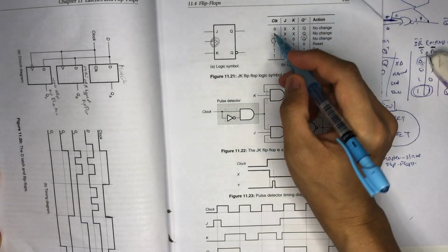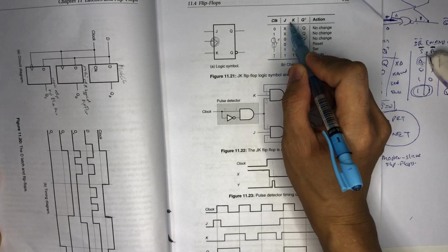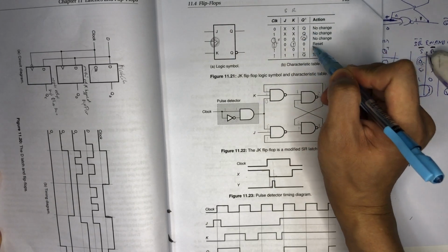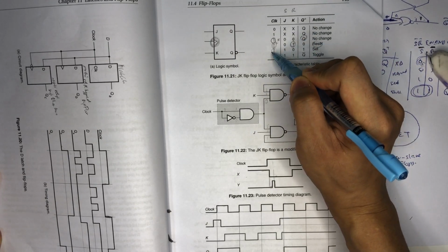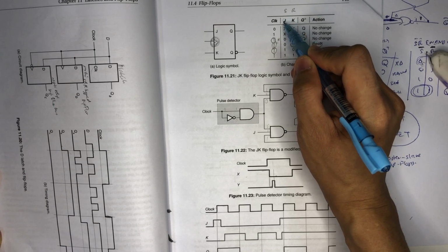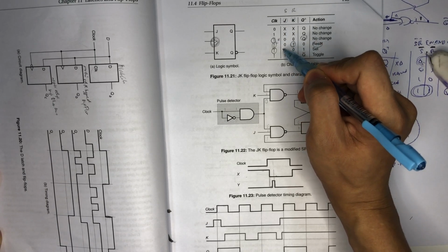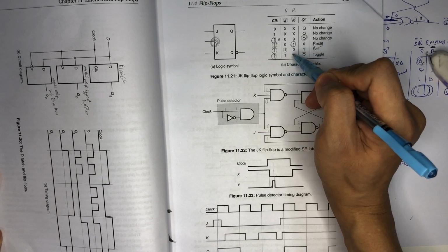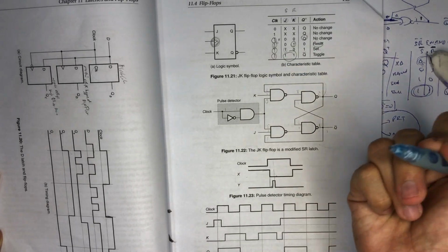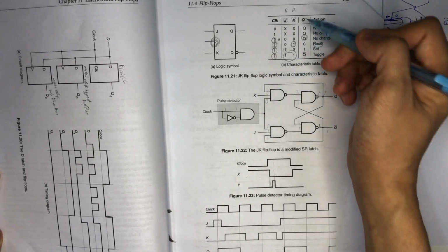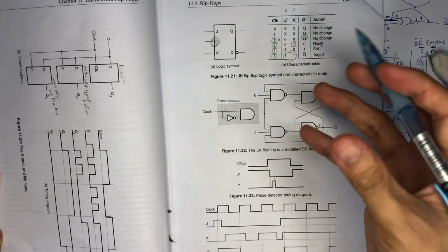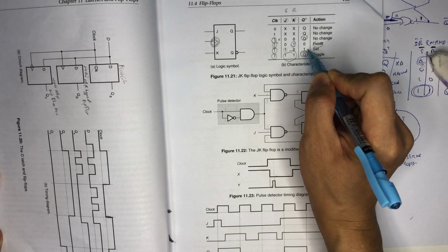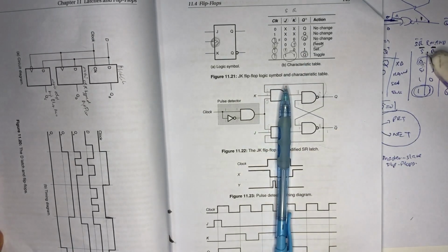Then at the next edge trigger, say we have JK here as 0 1, just like the SR latch, this functions as reset, so you have reset. At the next positive edge trigger, if your J is 1 and your K is 0, then you have a set function, 1 0. Then at the next positive edge trigger, what if you have both 1 1? In the SR latch, this is simply forbidden, but in JK we have this different operation, which is toggle. We will have toggle, so the inverse of the previous output.